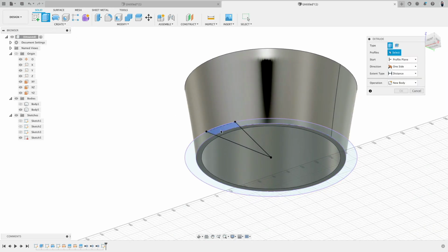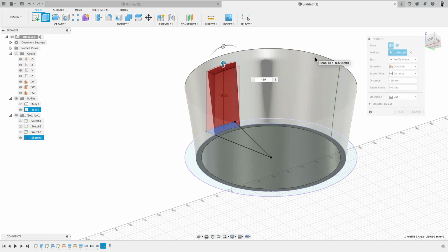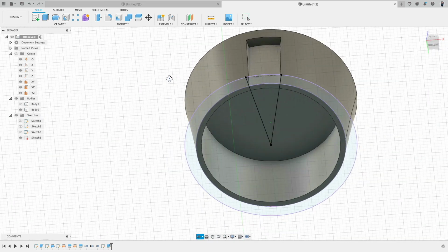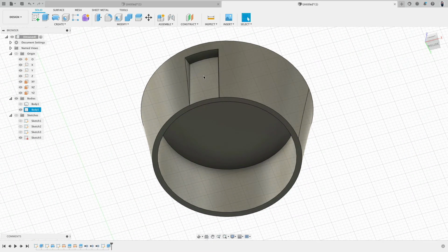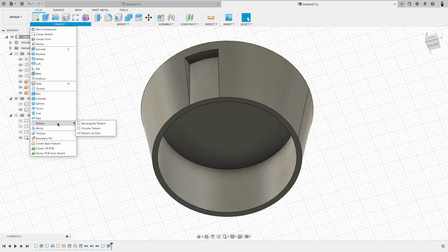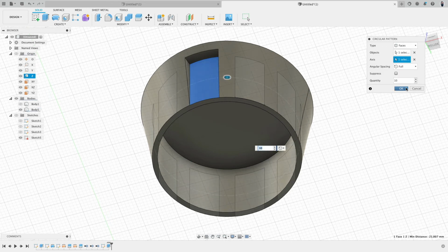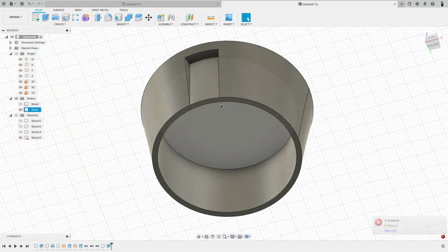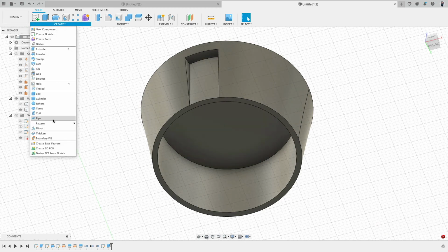Cool. Extrude this profile up, maybe minus 90. That looks good. We would like to have more of these features or surfaces. So create pattern, circular pattern. Faces and features sometimes might look the same. If I select this face and then go to here, 10, yeah, doesn't work now because I can't make this face in a volume. It's not logical.